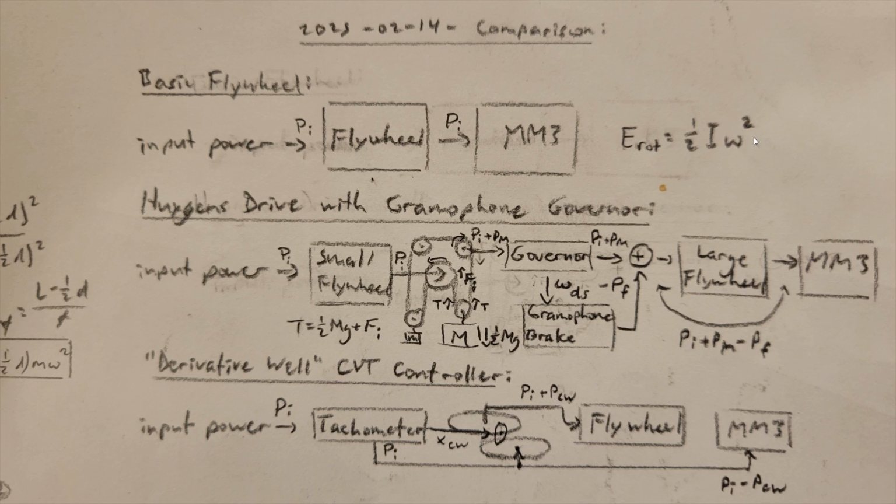Said speed can only be changed when there's a corresponding change to the energy of the system. As for how that is done, that is through the application of power, which is measured in watts or joules per second. Positive power to increase the energy and hence speed can come from user input or a mass, while negative power to decrease it can come from friction or from the loads on the machine, such as lifting marbles.